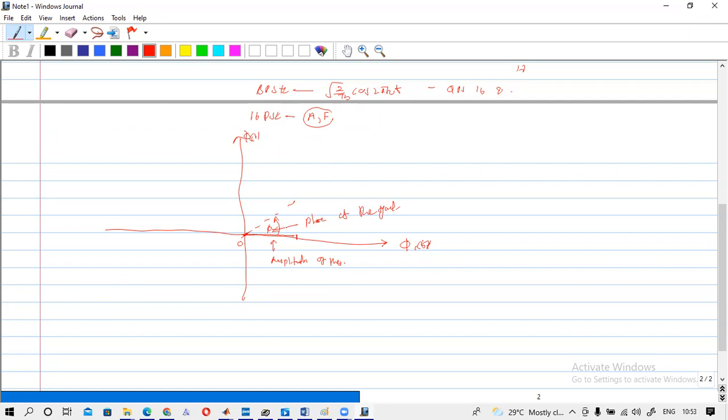So you can see that in phase shift keying, you are not changing the amplitude. You will have the same amplitude for any point. If you draw a circle with the required amplitude, all points will be on this circle. Is it clear? If you have any problem, you can ask.